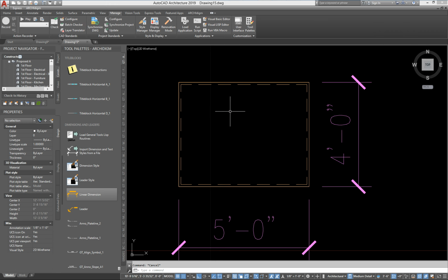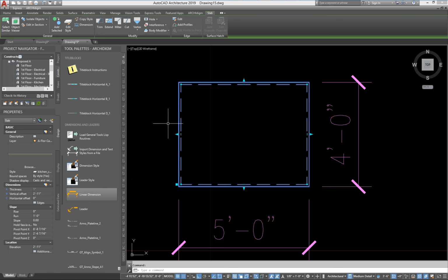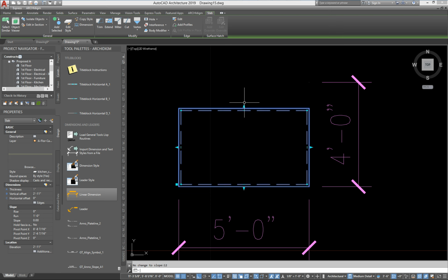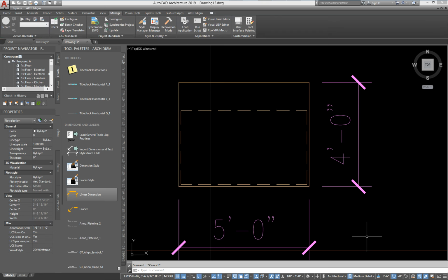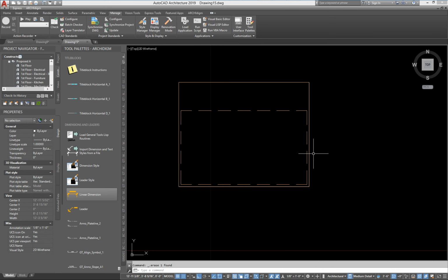And so what we have here is an outline showing the body below. And what you can do with that outline, if you want to show that this is an island with a sitting area, is pull the body back, say 12 inches, and then pull the overhang out like so to show that this is the area that will be a sitting area. So if you were just worried about plan view, you could probably call this done. In plan, that looks like a kitchen island with a body underneath. But to make it more realistic in 3D and for elevations and renderings, let's keep working.